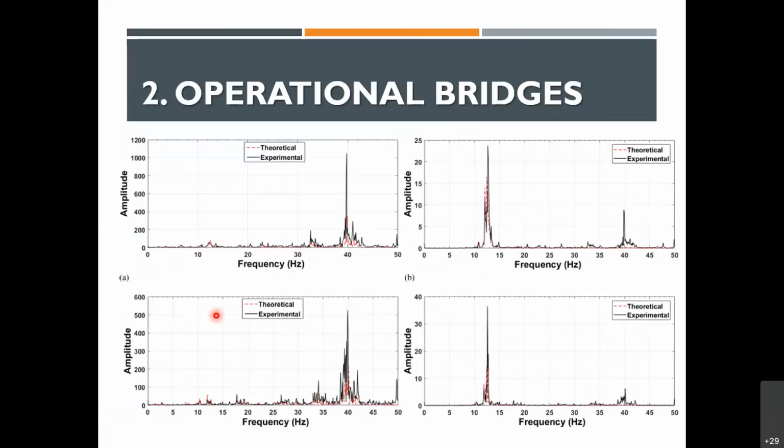Next, we started taking just a basic Fourier transform of these things, but that was obvious, the location of the frequency matched quite nicely. So at least in terms of changes in fundamental frequencies and those kinds of things, it's good, because now we have a project called CIRMA where we are instrumenting a train with various sensors, and we are making it go all around the network in Ireland, considering the moving train as a moving sensor on your network. So it was a good background idea behind it.